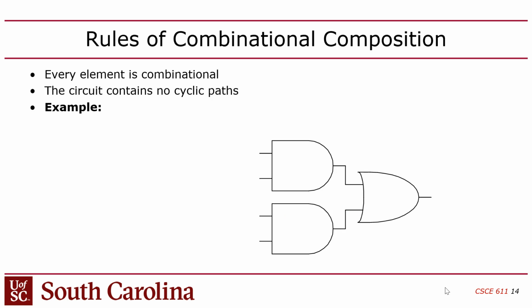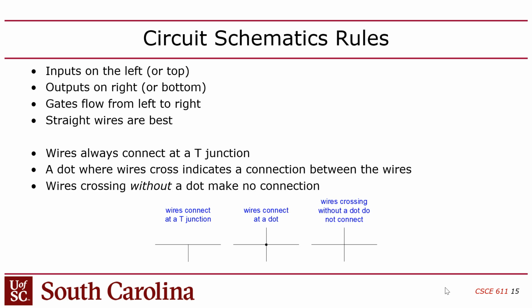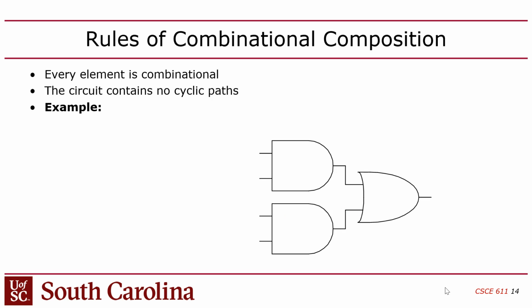So we're going to look at a lot of schematics in here because, basically, in order to make the CPU design easier for you guys, I'm going to give you schematics for the CPU. And you've seen these in your computer architecture textbook. Basically block diagrams, blocks connected with wires. And then your goal is going to be to transliterate them. You want to design those in SystemVerilog in a way that you can deploy them on the FPGA. Does that make sense? So you have to get used to reading these schematics.